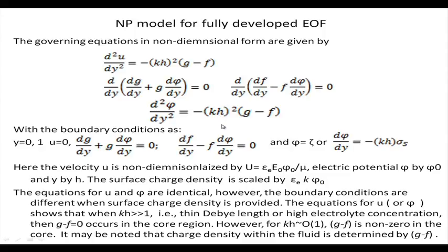So, if I prescribe kappa, which means the Debye layer thickness, the Debye layer thickness is also governed by the electrolyte concentration and the permittivity of the electrolyte and so on, which has already been defined before. Other things like temperature and the gas constant have constant values. But for the fluid, you can have a different viscosity, different permittivity. So these parameters are all grouped together to form this kappa h, and this is u, the Smoluchowski velocity.